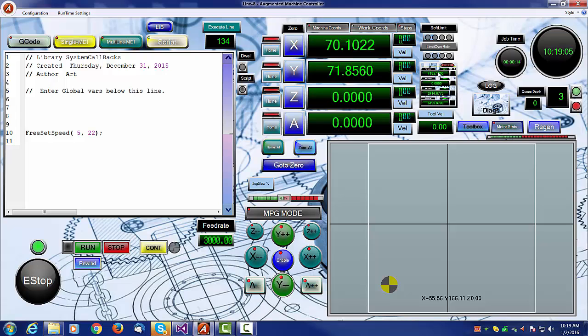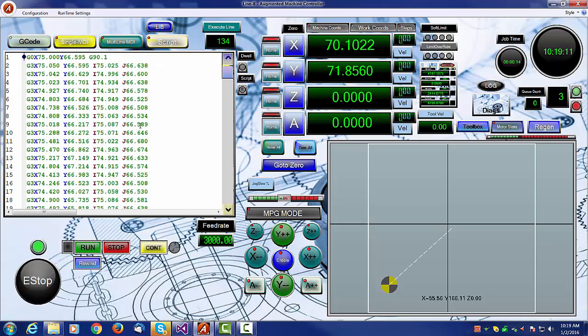They're being set up as a separate Cartesian system that can run in parallel with the original one. So while you're running G-code, you could trigger a script that tells these 3 stepper motors to move to a tool changer position, grab a tool, and maybe this final one flips a lever or something, who knows. But they are a parallel system.